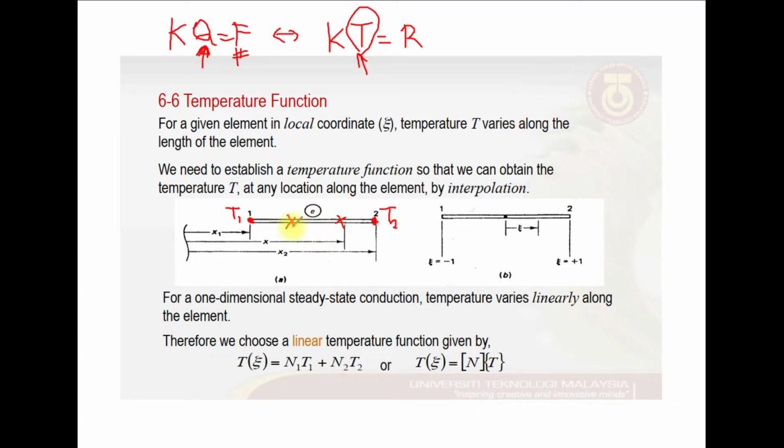Thus, to determine the temperature or temperature field within the two nodal points, the interpolation technique must be applied. So in this case, we'll limit our discussions to the linear interpolations as well, similar to the one that we discussed in the structural problems.